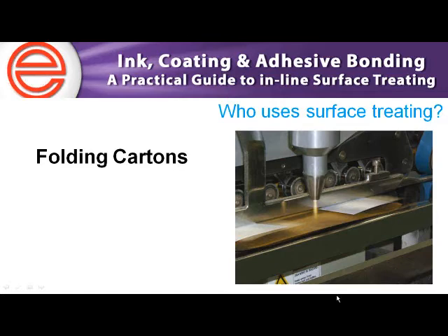With surface treating, we're able to replace the skiving, which is a bit of a messy process with wear parts on it as well. What we found is that oftentimes the bond strength becomes so great that if a folding carton is a secondary package, you may be able to remove the primary package. We actually had this in a food product where the company was able to increase their glue flap strength, eliminate a primary package, and use the folding carton itself as the primary package.